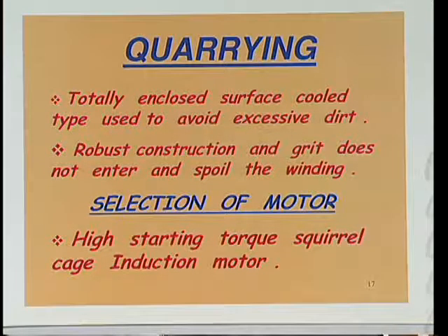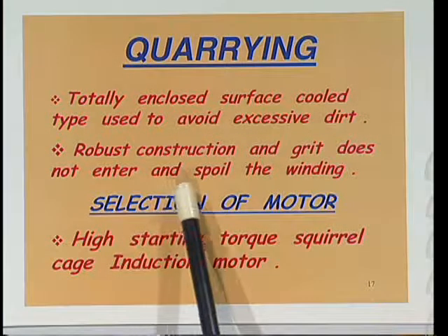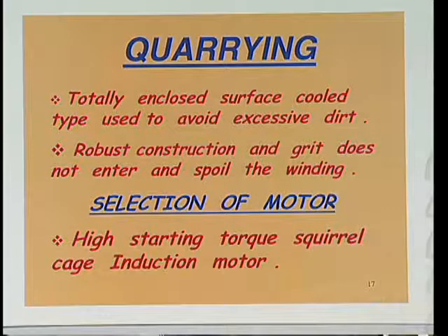So totally enclosed and surface cooled motor is more useful for quarrying because a lot of stone dust will be there.